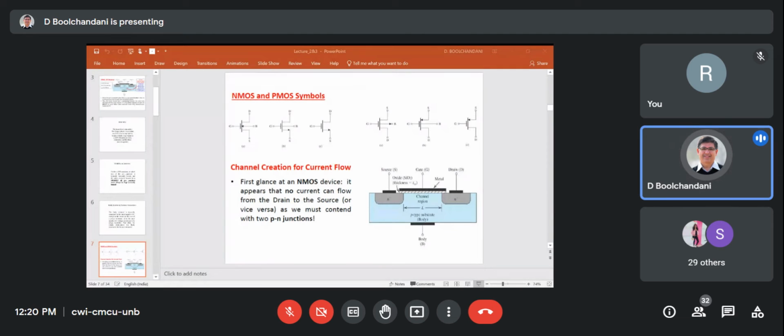These are the typical symbols for N-type MOS circuit, right? The current coming out of the source terminal, right? You have a substrate terminal also indicated. Sometimes you don't have a substrate terminal, but this current is coming out of the source terminal. That means it is an N-type MOS. If the current is going into the source terminal, it is a P-type MOSFET.